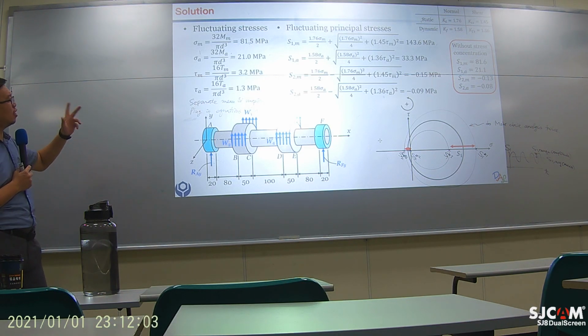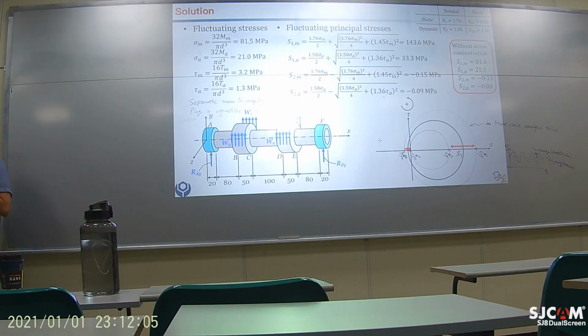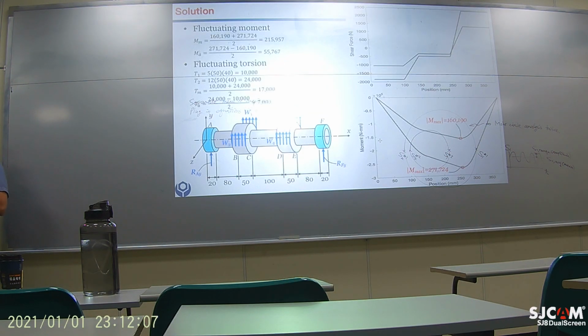So earlier we had the moment diagram, and from here we found the two extremes. From the two extreme conditions we studied the mean moment and the amplitude moment.